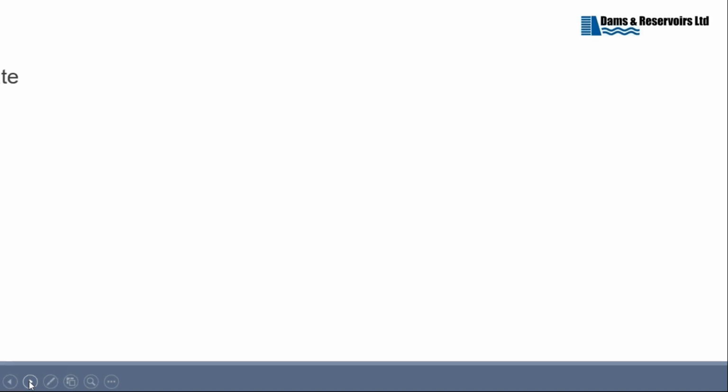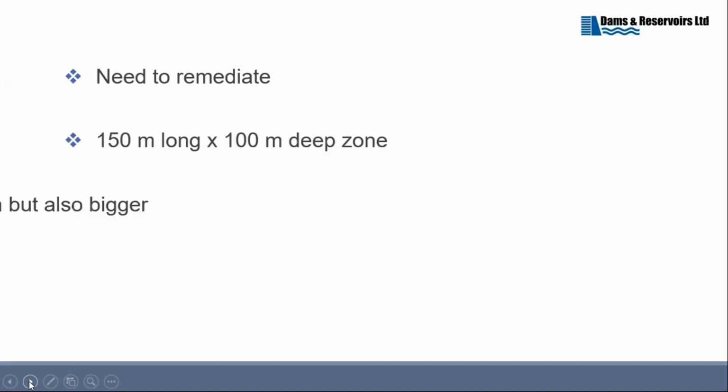So I went back to Austria and we identified a zone, because when I went into a room of 5 geologists, they said, "We've drilled 900 meters of boreholes and you're absolutely right. We have found the leak. We can see it tracking down the outside of the gallery, down to the bottom of the dam. It then goes under any fill we've put underneath the dam, and it pops up in various places. So can you tell us from your survey what sort of zone we need to grout?"